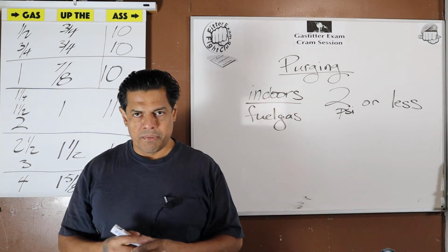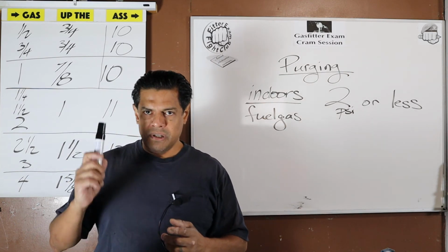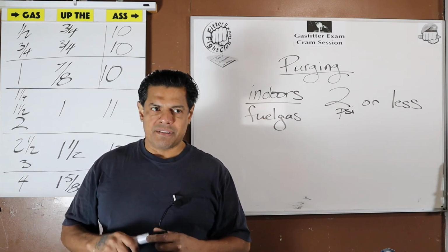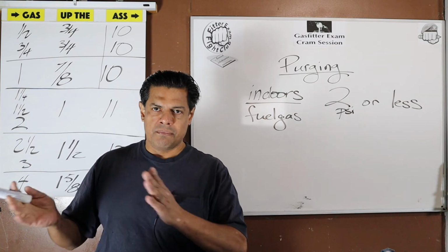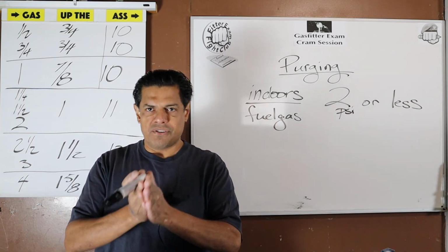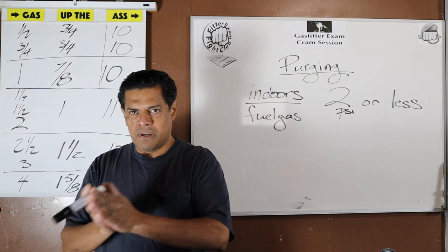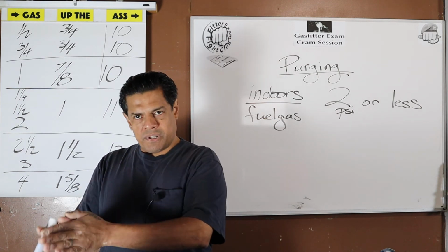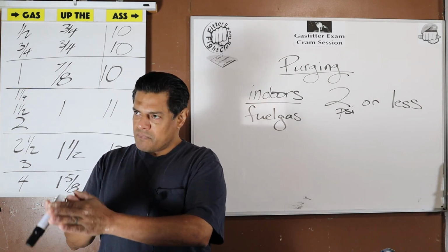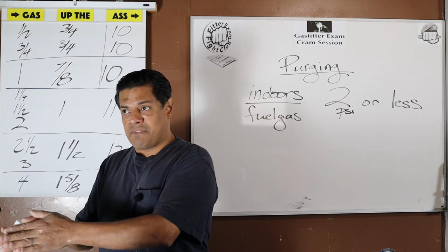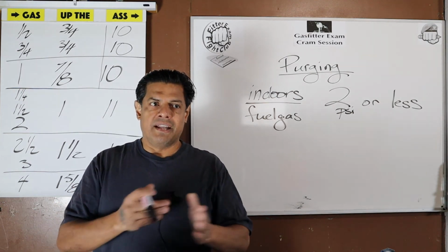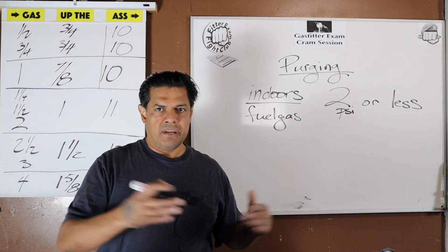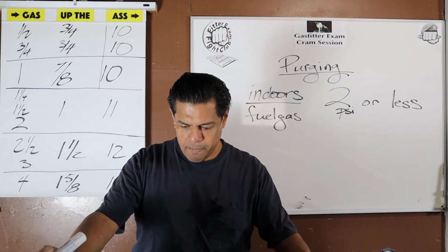Left-right nipple and coupling, but no union. Union is strictly for the appliance, and it's got to come downstream of the appliance shutoff valve. Keep trying to use their word and call everything officially what they want it to be called. So, the appliance shutoff valve is not the same thing as the lockable supply valve that you might see at the base of the riser.